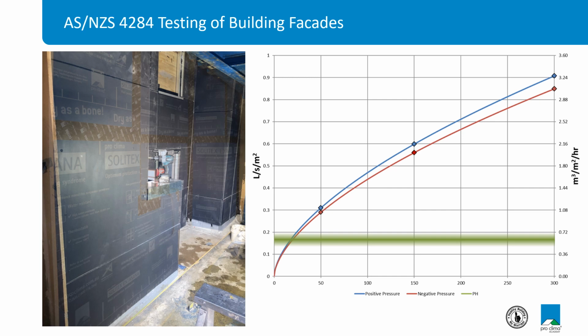If we're shooting for Passive House, in terms of air permeability of the facade, we should really be down around 0.6 air permeability, because we know that based on the surface area to volume ratio of a building, permeability and ACH 50 are roughly similar, but they can differ slightly. But we would still need to target around 0.6 air permeability to even be in the ballpark to achieve Passive House thresholds.